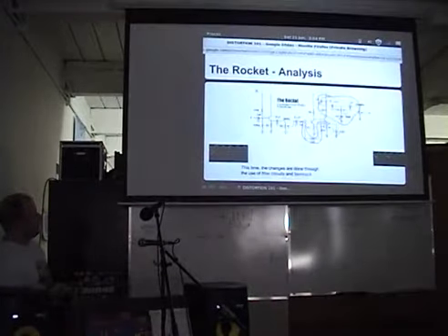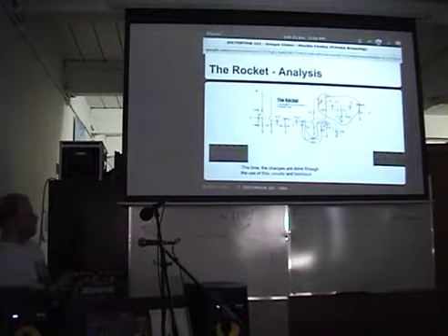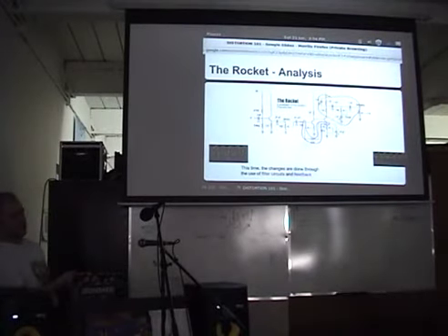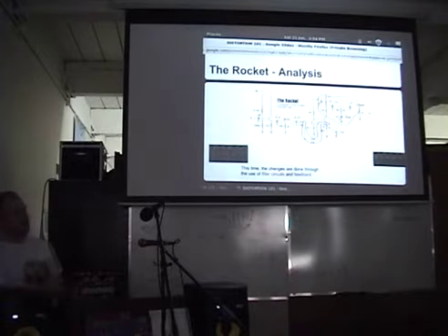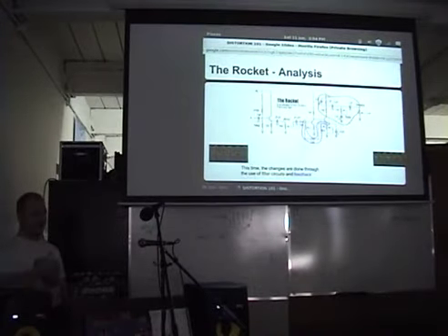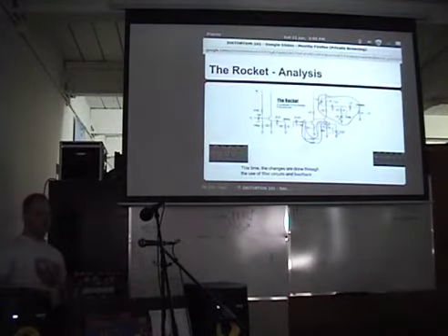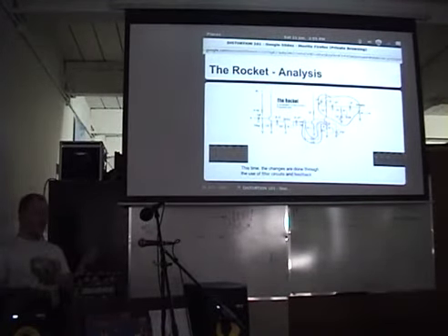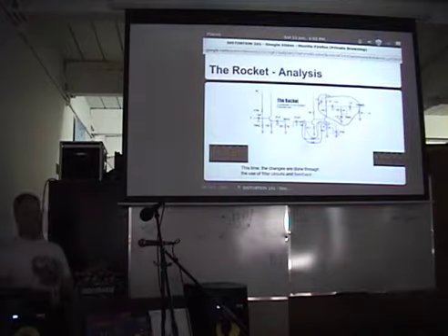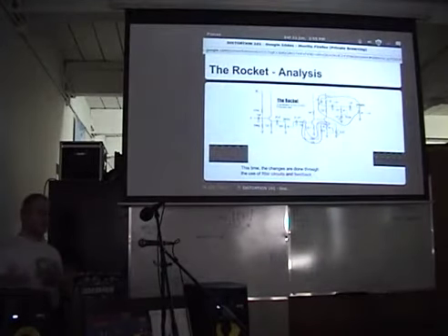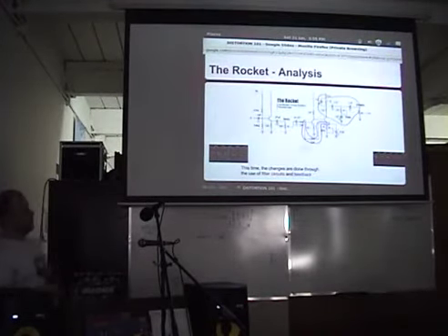And then there's this other stuff in here. You see we have this capacitor labeled tone, and capacitors all over the place in here, which effectively act like frequency dependent resistors in a way. They present one load at one frequency, but a different load at another one. So that's how you can make circuits that amplify some frequencies and not others.